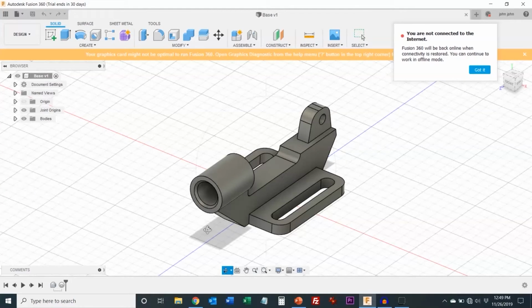Well, these side actions are mechanical pieces, so when the mold is closed, these side actions are pushed in so that this hole doesn't fill with plastic and this hole doesn't fill with plastic. But then when it's time to remove the part, instead of just opening the mold and pulling it out, you now have to remove these side actions. The side action would be pulled out, and then this side action would be pulled out, and then the mold would be pulled apart and the plastic piece would be removed.